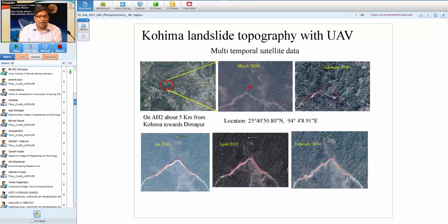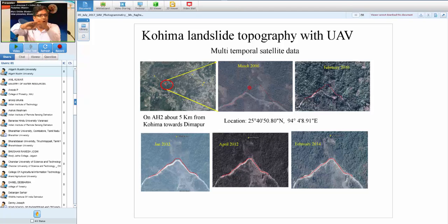So for the landslide, we made use of the terrestrial laser scanner, which is costly, which comes with a cost of around 70 lakhs. And this very costly terrestrial laser scanner gave us the high dense data, definitely, but it has some gaps. However, it is a very costly and sophisticated technique. Even with that technique, we could get the data only with some gaps or holes because of the local undulations on the landslide. We are standing on the ground and the landslide is there, and if there is any local undulation, these local undulations are blocking the area, so we get the holes here.